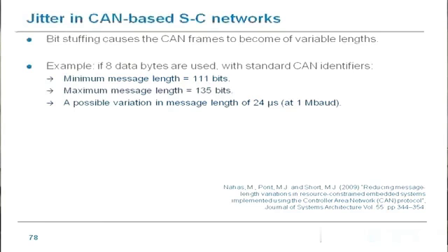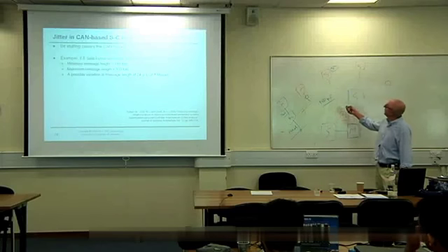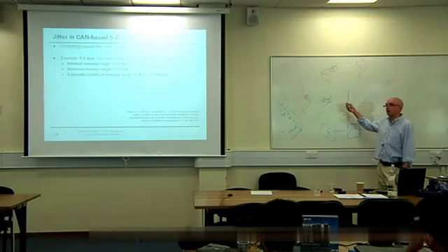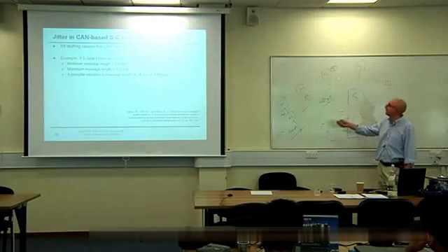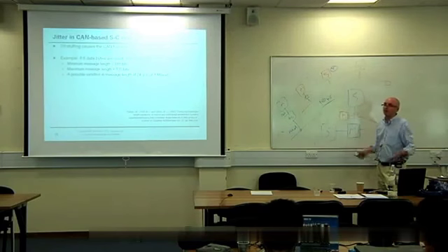That's a lot. That's way at the level where we wouldn't consider it possible to introduce, in many cases, in a single processor system. So we've got the possibility that the timing here is varying by 24 microseconds in tick. We've got a significant level of jitter.